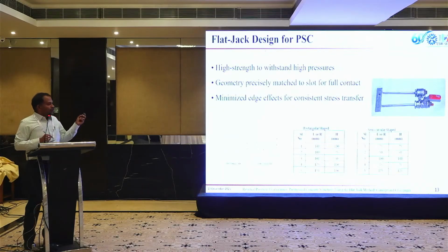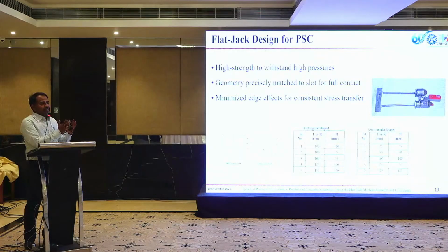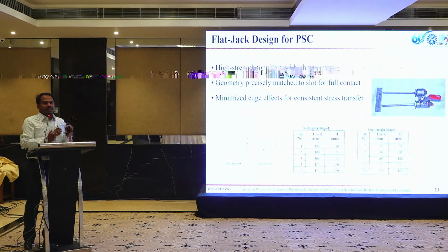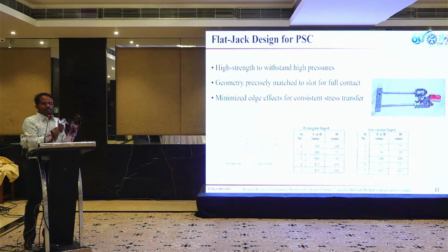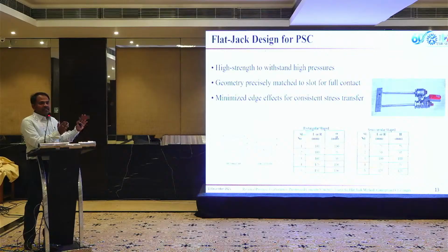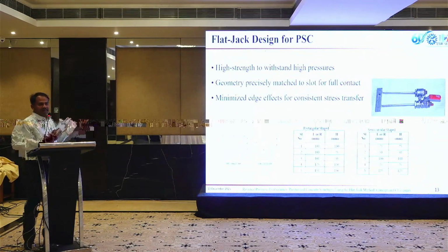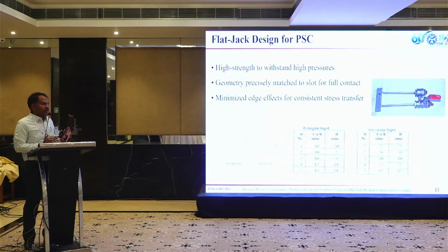Normally you see the reinforcement spacing at a minimum of 100 mm to 150 mm. In the case of pre-stress, the reinforcement is not a major component in taking the loads, only the pre-stressing force. So the minimum spacing of the reinforcement will be 150 mm, and the slot size or maximum flat jack size is restricted to 150 mm.